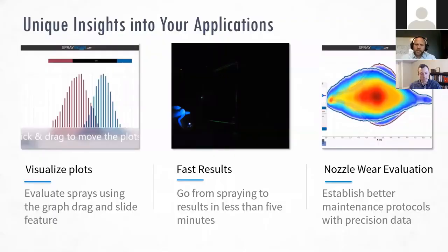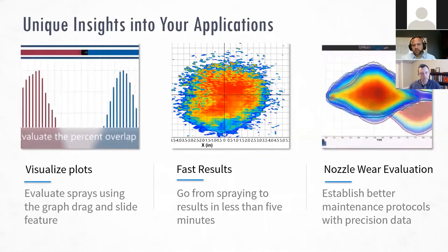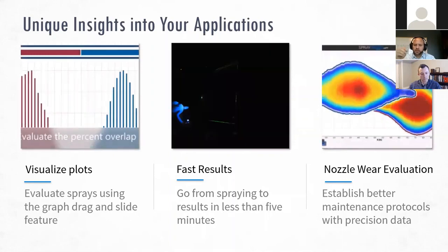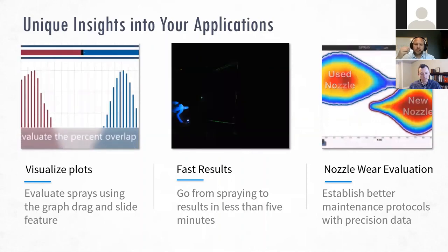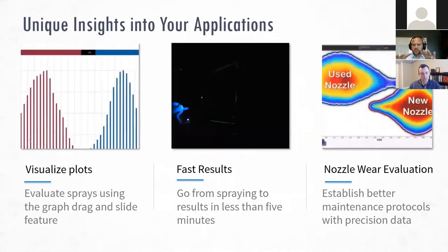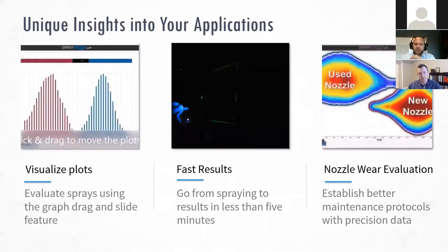There's a particular application I can recall. A client was flowing through over 9,000 gallons per minute, and at a pretty good pressure. And just a small variance in the orifice or the flow rates, which was marginally detectable by their pumps, could be noticed very quickly, preemptively by a spray scan. You would have the ability to see what that distribution does, but also that correlation coefficient between a healthy nozzle and what would be an unhealthy nozzle.